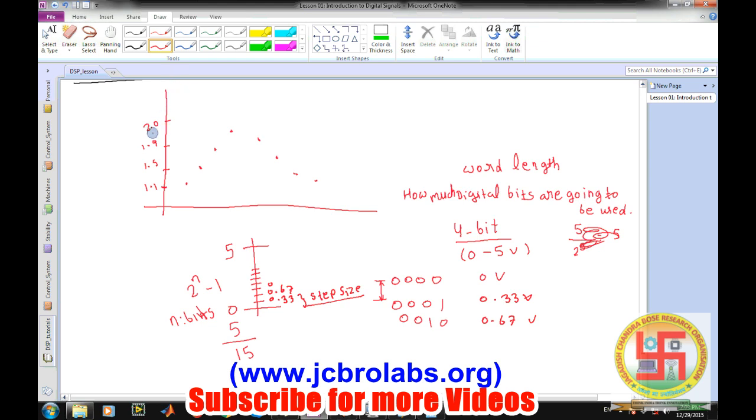So what does the quantizer do? The quantizer converts any value to the nearest level. For 1.1, the nearest level is 0.99, since 0.33 multiplied by 3 is 0.99, and the next level is 0.33 multiplied by 4, which is 1.32. So 1.1 would be brought down and treated as 0.99 volt. That is what is done in the quantizer.